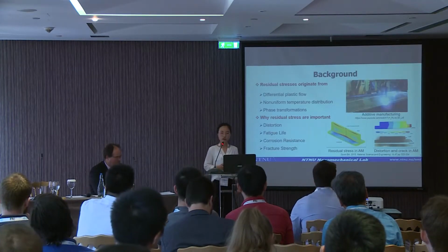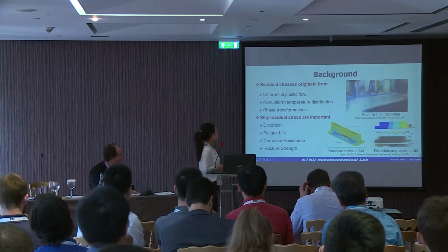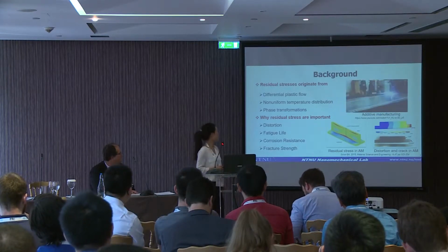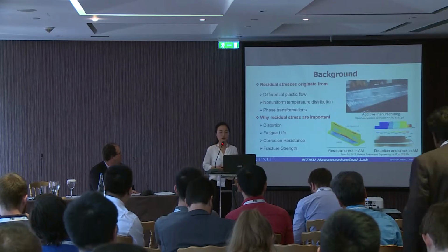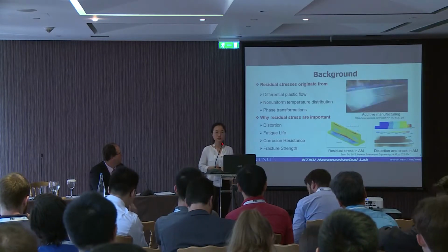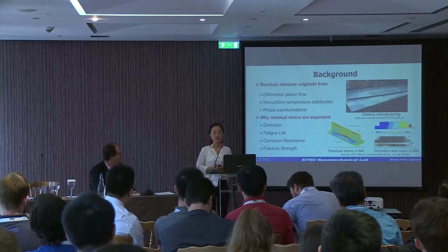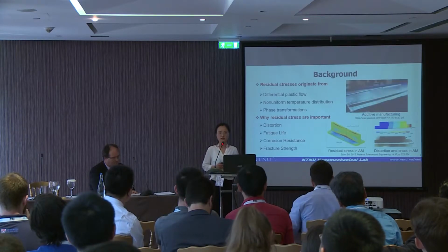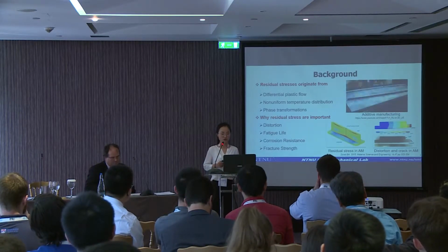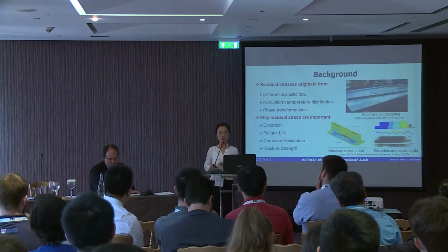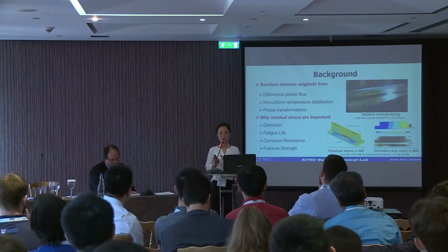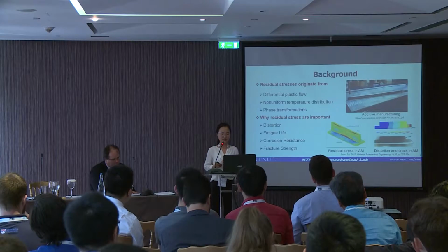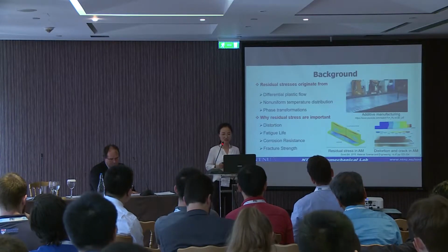And residual stress can bring distortion and reduce fatigue life, corrosion resistance, and fracture strength. So for additive manufacturing, residual stress is a big challenge, and predicting residual stress is important.